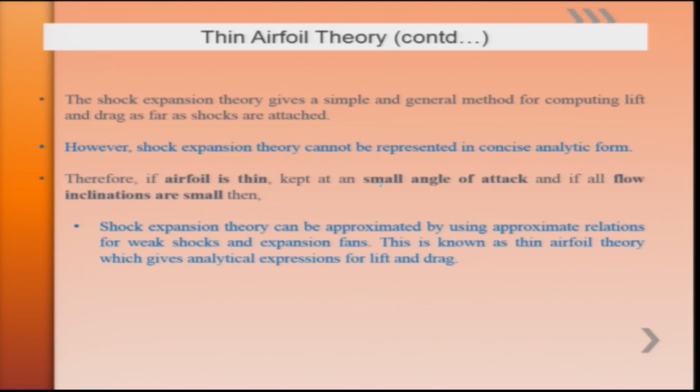Assuming the airfoil to be very thin, kept at a very small angle of attack, and further that the flow inclinations are also small, shock expansion theory can be made using approximate relations for weak shock and expansion fan.